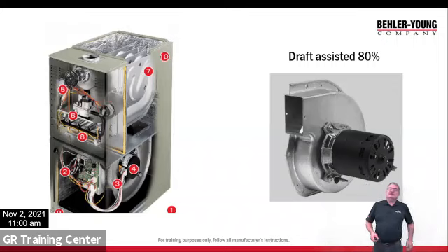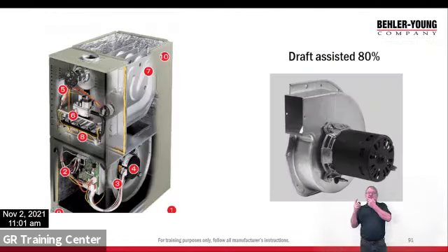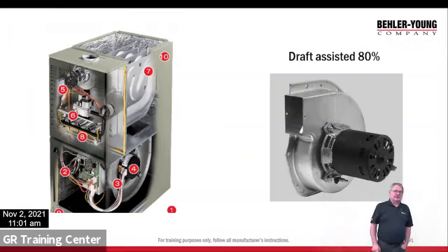Okay, so we were able to get more efficiency, because we needed to squeeze more heat out. This old furnace over here on the right, or that one in the center, might have been 60% efficient or less. Now we're getting into the 80s with this fella. If I look on that furnace over there, you can see it's at the top. The burners are still in the bottom, so it's drawing the flue gases from the top of the heat exchanger while the burners are still sitting in the bottom. And then from there, it goes into a chimney.